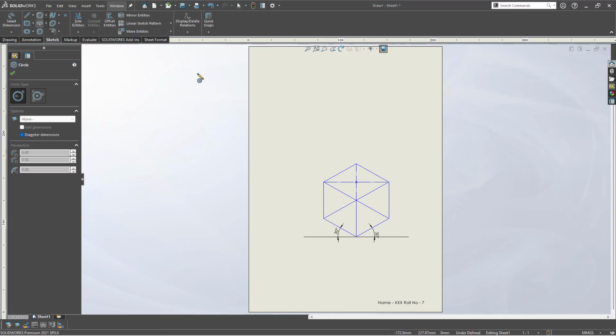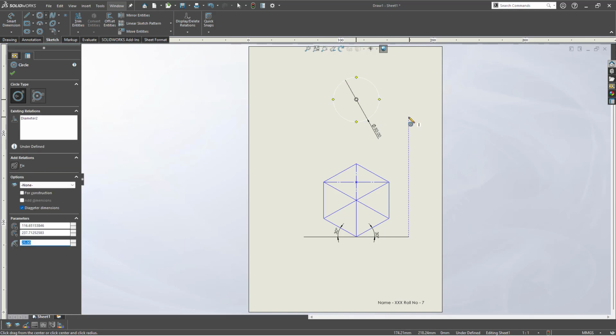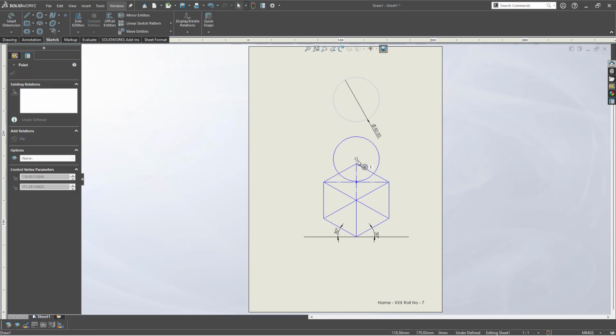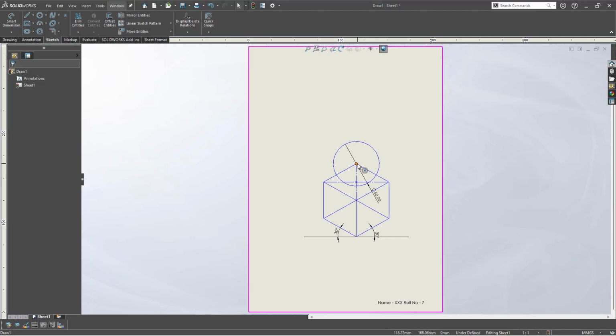So you can activate circle. The shortcut is again C. Okay. And you can just draw 50 somewhere here. Now I should place this one exactly here somewhere. So it should lie on this point, because in isometric view it looks like this, okay, on this point. So if you now measure from here to here, it should be exactly 50, correct? You don't need to drag and drop it. You can measure the value, because you can see from here to here it is radius 25.